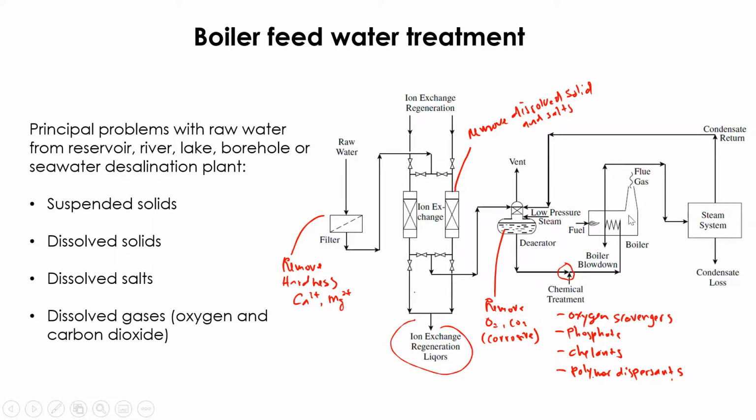After undergoing a few steps of the refining process, the water enters the boiler. In the boiler, you see here you have two streams for the water. The first stream is the steam itself. The other one is the boiler blowdown. The objective of the blowdown is that after a lot of pre-treatment, you will still eventually have some solids in this stream. Since the steam is free from solids, you will have solids accumulating inside the boiler, and to prevent the accumulation, there is a boiler blowdown system.